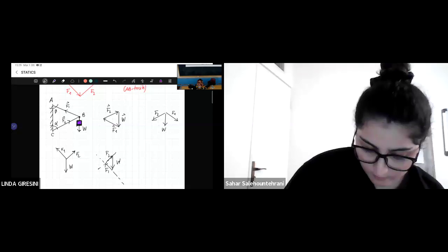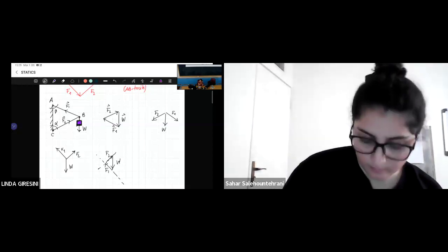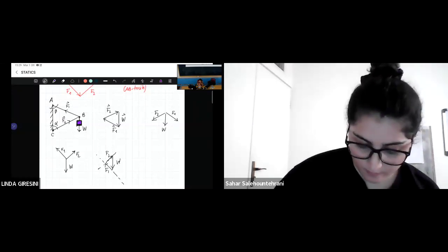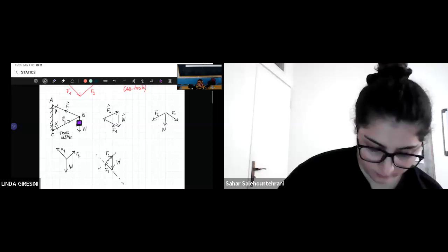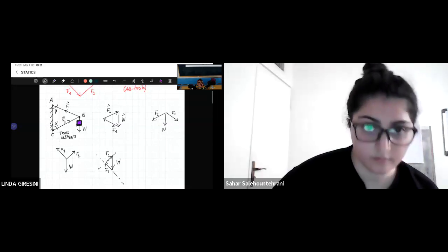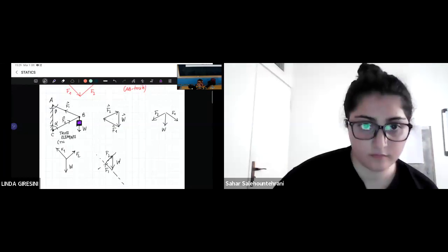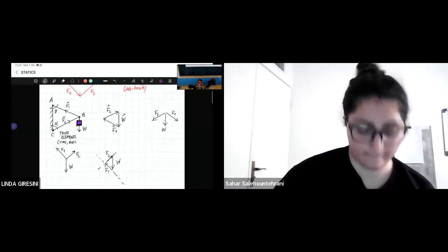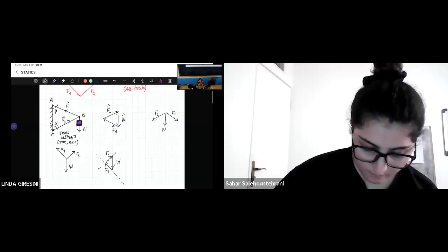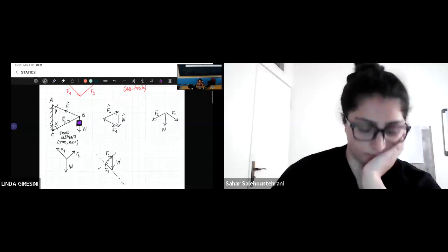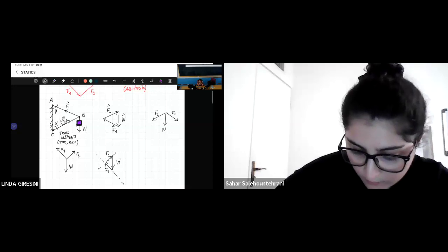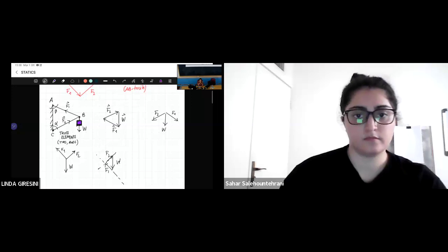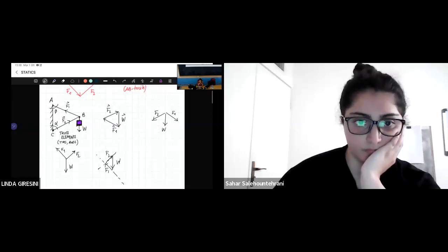And we had these two structural members. These are called truss elements. They can be subjected either to tension or to compression. We call them, as you remember from last time, ties or cables, and rods for compression elements, or truss elements. And you were asked to find F1 and F2, which are the forces in the elements AB and BC respectively.